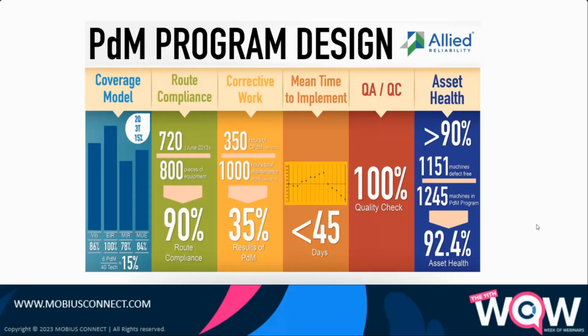And then have a good QA/QC process in place. You take corrective action on an identified defect. Have a process in place to go back using the same technologies to verify and validate that the failure mode has been removed. And then a leading indicator is asset health. You're targeting 90% of your total asset base that has condition monitoring inspection across all of your technologies in place, 90% to be healthy, with no identified defects, as a target. And in this example, 92.4% asset health. Leading indicator, what you can expect from a reliability performance of your asset base moving forward.